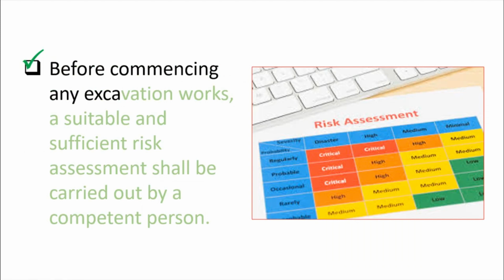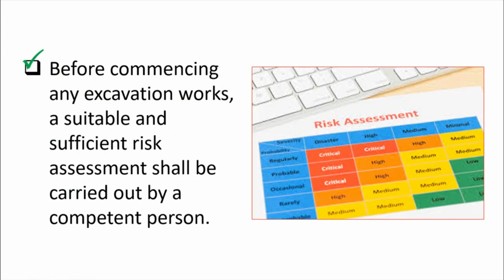Before commencing any excavation works, a suitable and sufficient risk assessment shall be carried out by a competent person. A competent person, as I discussed, has the knowledge on how to prepare the risk assessment. He has the skills on how the job is done properly.